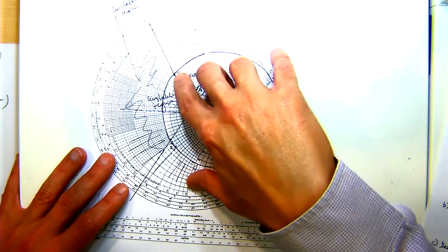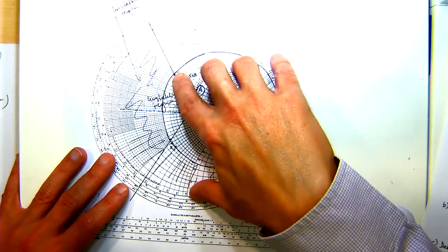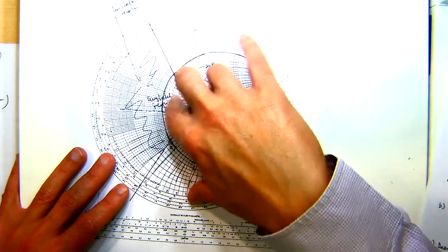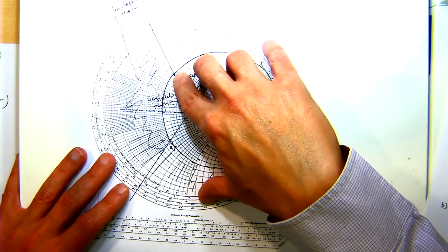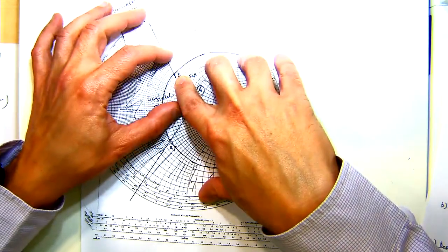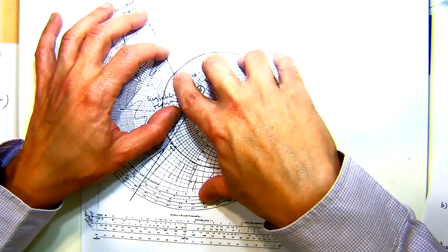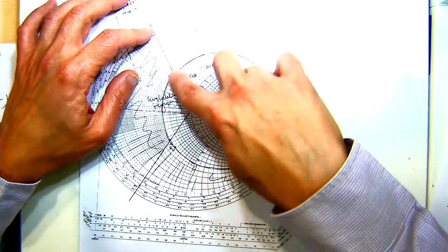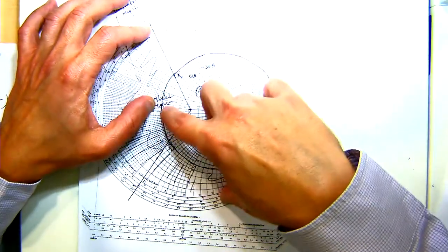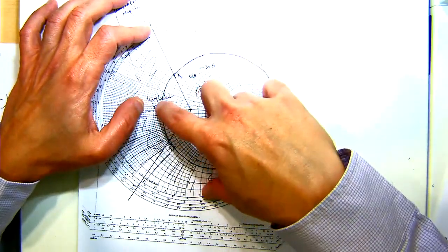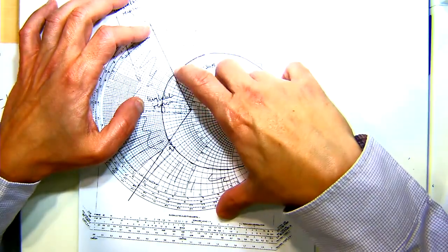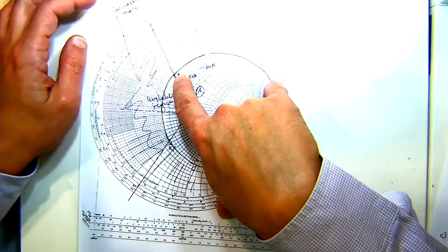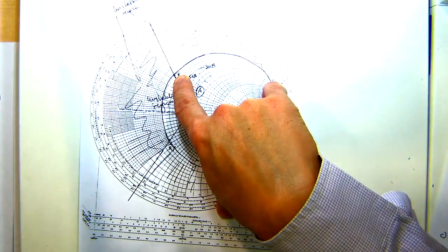So I've drawn the gain circle here. This is 1 on S11. This is the gain circle, and this is 1 on S11. All I've done is draw the point of maximum gain, and then the value of this circle, which is of constant resistance. That's the point of maximum gain. Then I'm asking you to tell me which regions are stable and which regions are unstable.